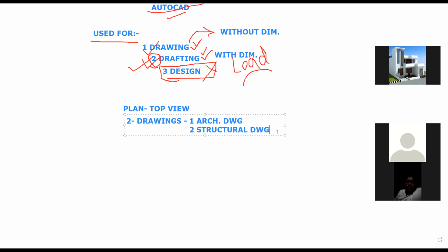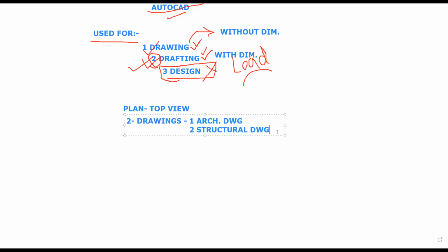You have to show them the amount of reinforcement used and the diameter of it one by one, and how it is going to look if we actually distribute the web of reinforcement over the structure over which concreting has to be done. So all these you have to understand by using the structural drawing.